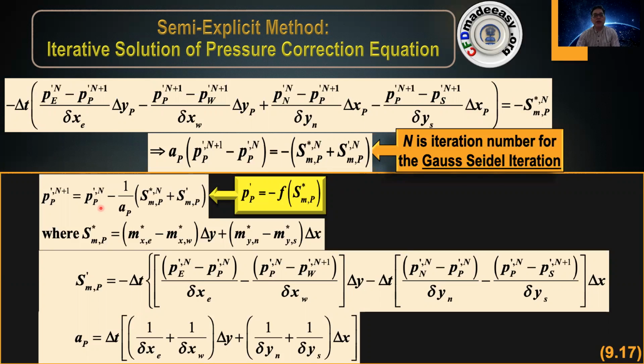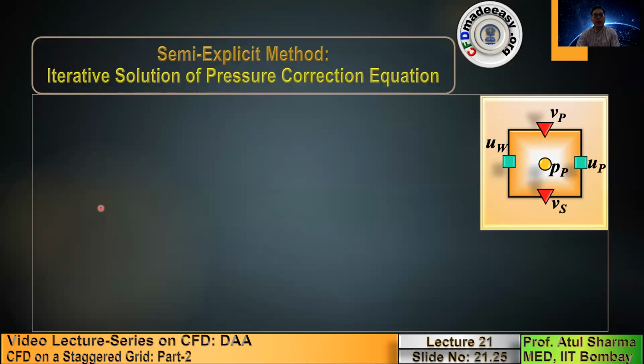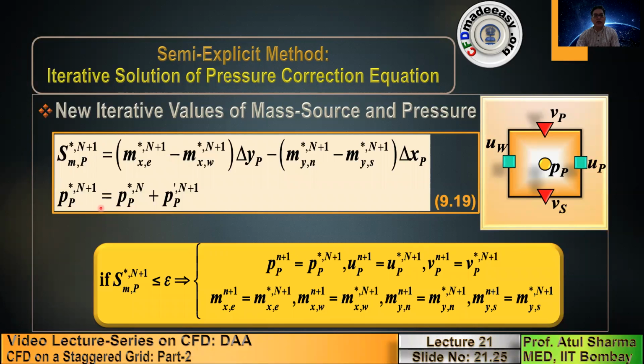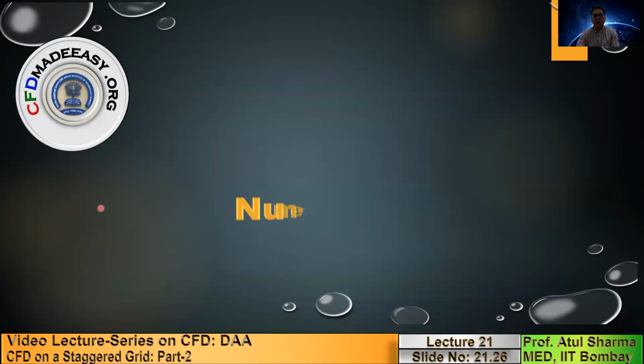Whatever step by step I mentioned in the solution algorithm while presenting the philosophy of pressure correction in the beginning slide of this lecture, I am following exactly here through the series of equations. So this gives you a better connection between the philosophy and the math being followed, which ultimately leads you to velocities and pressure of certain iterations that obey the mass balance. Only then do they become the true velocities and pressure for the next time step.